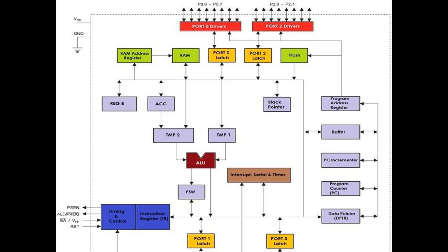I think how many of you remember the various flags which we learned in the case of the 8085 and 8086 microprocessors? We already learned the 8085 and 8086 microprocessors in previous classes. Now we are discussing the 8051 microcontroller. Let us have a small comparison between these two, like flag registers. If you see the 8086 microprocessor, out of 16-bit size we use 9 flags, but when it comes to the microcontroller, out of 8 we use only 5 flags.